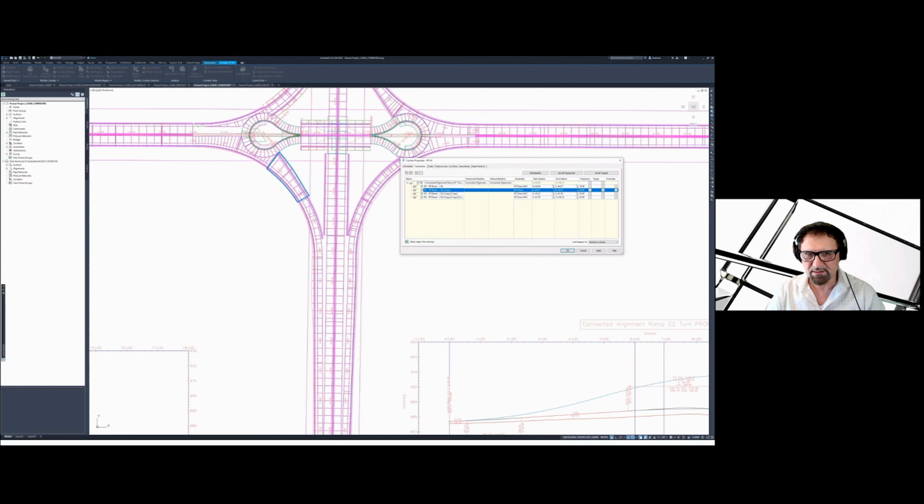direct ramp. That's a full ramp program with daylight lines and catch points there. And then no left catch point. And then I have something that even doesn't have a shoulder. Now this area here will be a separate gore area. So I'm going to target this edge from the main line so that the main line is going to extend all the way from where the nose is.